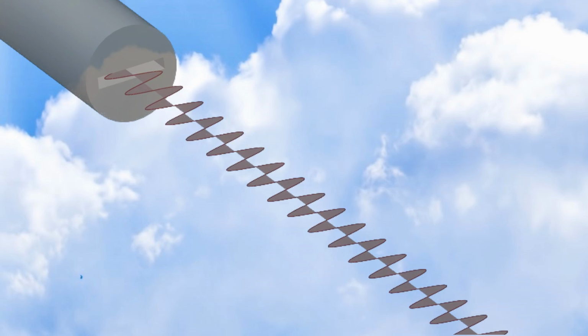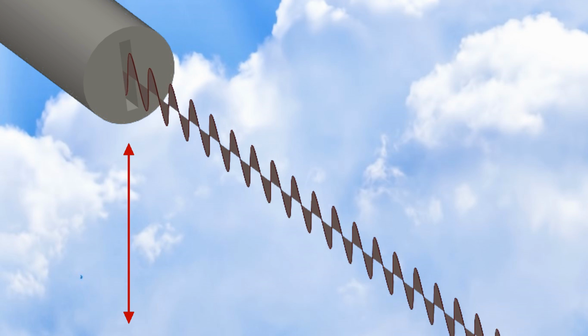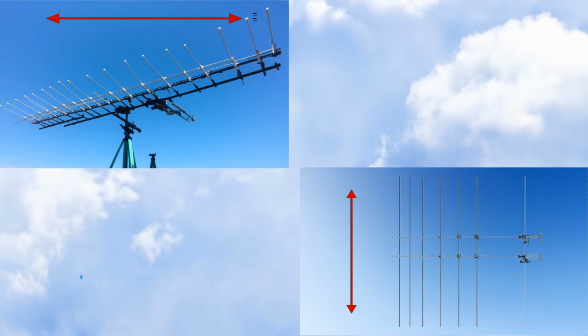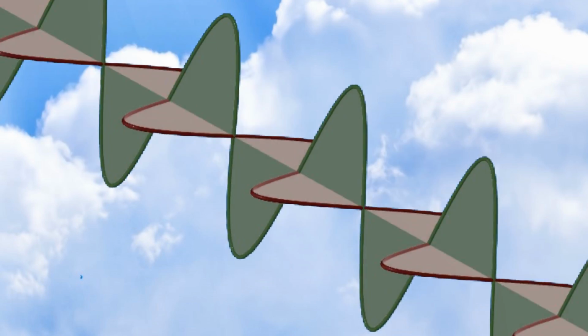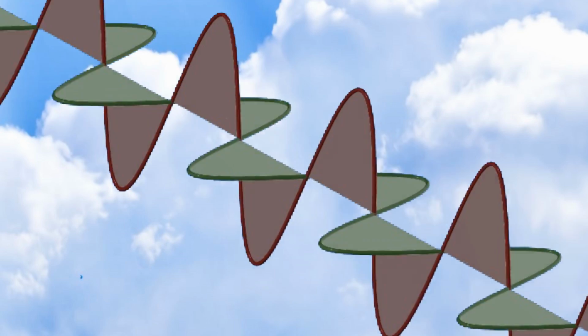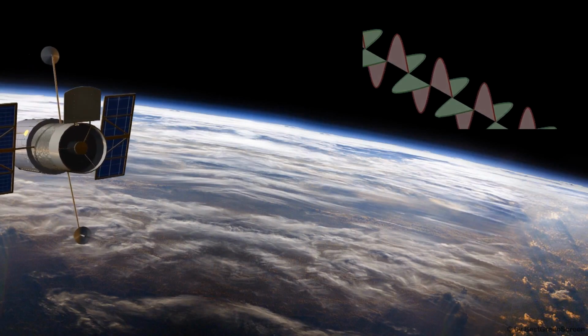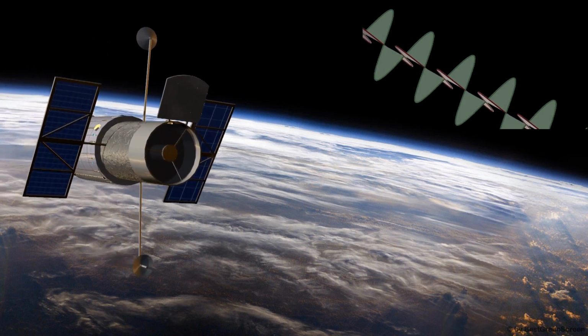Most technical applications are linearly polarized, either horizontally or vertically, and are aligned with the receiving antenna's horizontal or vertical wave orientation. However, there are also applications where the EMF wave rotates. The rotation direction of electromagnetic waves refers to the rotation of the electric field, either clockwise or counterclockwise, called circular polarization. This concept is significant in technical applications, such as certain Wi-Fi systems, satellite communications, radar, and 5G networks.